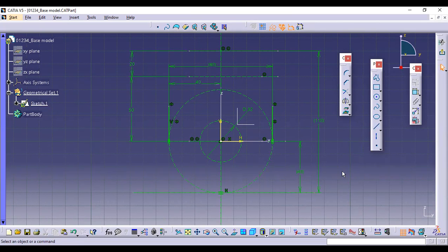Refer to the drawing, you'll come to know. The 80 mm is already mentioned in the drawing. That's the reason we have used 80 mm also. Apart from 80 mm, we have used 40 mm, which is from the center of this, because we need this line. So till now, any doubts here? You'll come to know what commands we used, why construction lines are required, and then going forward how we are going to use them.